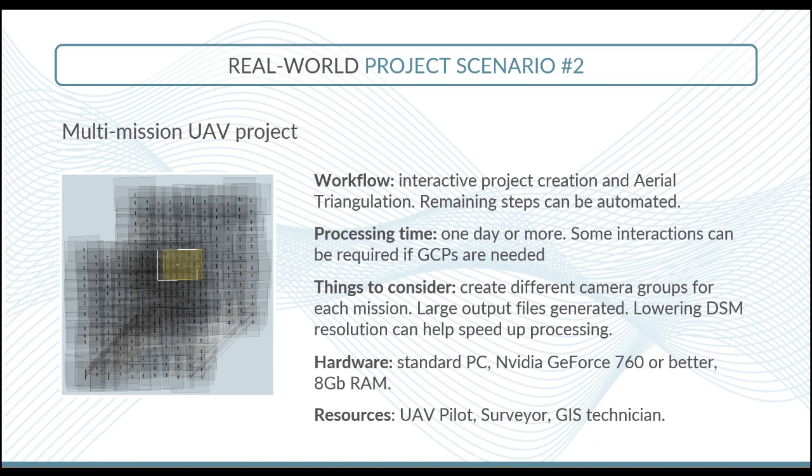Things to consider: you will have to create different camera groups for each mission. This will help the aerial triangulation. And you have to keep in mind that large output files will probably be generated. So when it's time to create a mosaic, you probably want to tile your mosaic into different tiles. And also, you may want to ask yourself what type of resolution you need for your